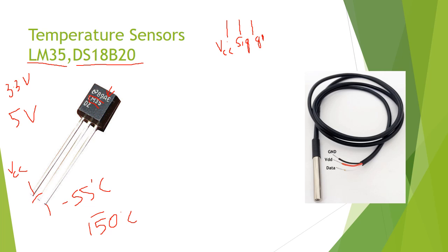The next question is, what is the data coming out? I have told you about these two pins. These two pins will be connected to your 3.3 volt and to the ground. So these two connections we have already done. Now this third pin will be going to the microcontroller. We will be generally using Arduino, and maybe we can go for Raspberry Pi.